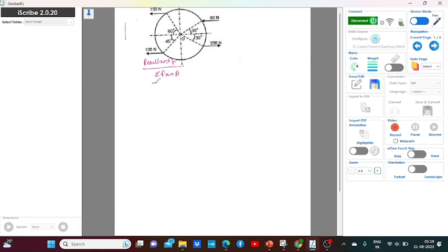So I can write it as minus 150, minus 90, minus 100, and plus 200. Okay, so that will be equal to what? If we just take the calculator, it will be minus 140 Newton. See, when we get the negative answer, it is proper to write 140 Newton and then you show it in the diagram like this, in this direction.